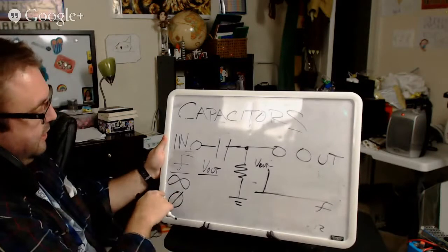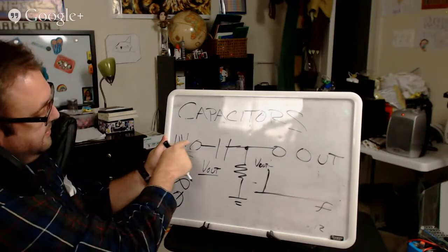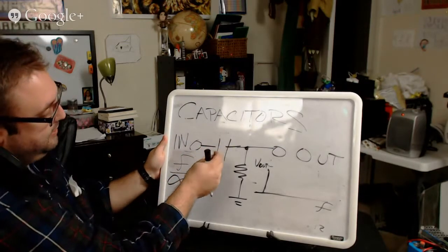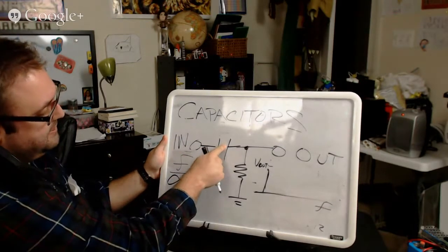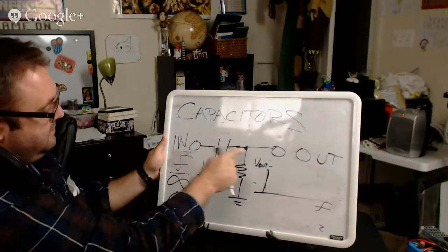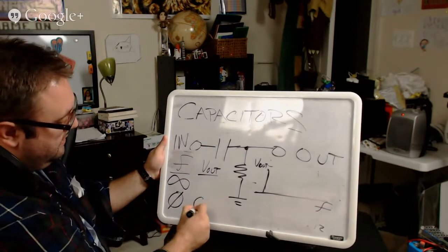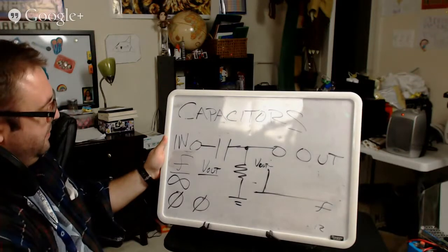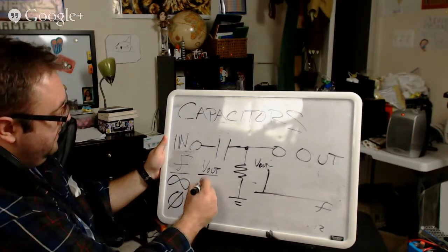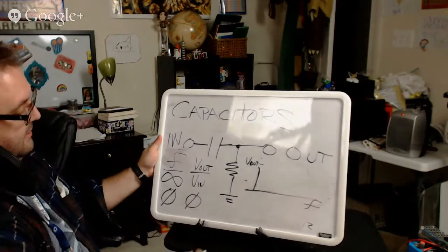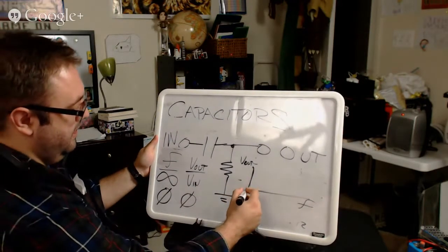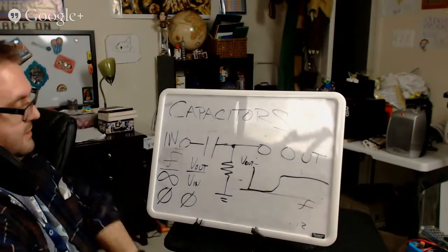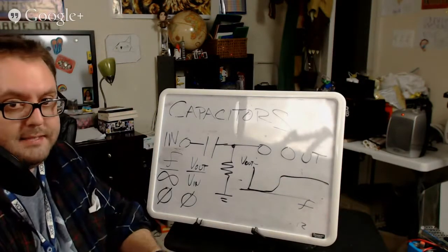A low frequency, I'm going to come in. Well, I can't get through a capacitor, because at arbitrarily low frequencies, it acts as an open. So at low frequencies, I have 0 volts on the output, and at high frequencies the output is V in. So at low frequencies the output is low, low, low, and then it rises at higher frequencies. So low pass, high pass filters.